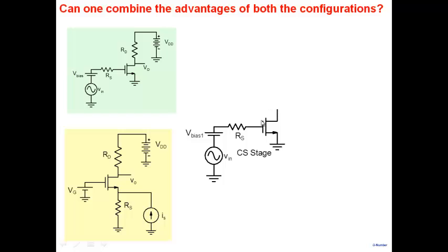Build a small signal equivalent circuit of this one. Will it look like this? At this node, what does it look like? A current source, gm VGS. What is VGS? Nothing but Vin, and an r01. Is this a good current source or not?